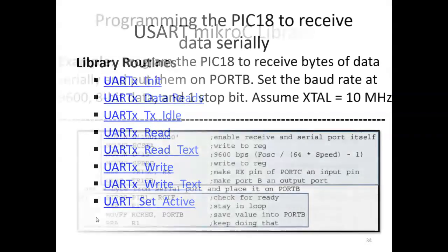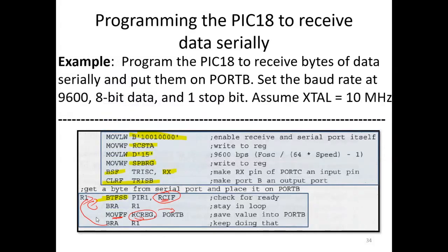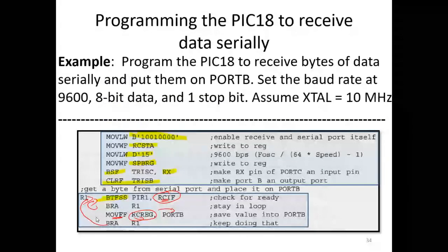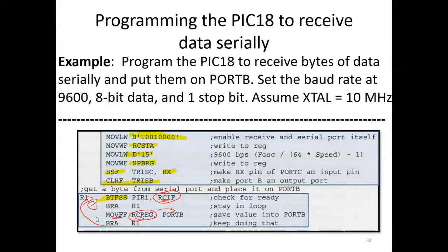So we have done for today's class. If we summarize, we have seen how to make the configuration of the serial port. We have seen an example of transmitting by using the polling technique and by using the interrupt technique. And we have seen an example of receiving by using the polling technique. So at home you can make an example of receiving by using interrupt. You can practice and do this.